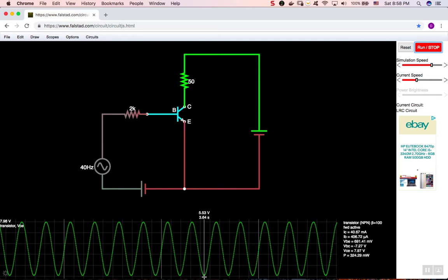So the voltage that appears across VCE is the same shape as the voltage across the small AC voltage source, but here the voltage only goes from half to minus half. So the range is 1, whereas here the voltage goes from 5.5 to 8. So the range is 2.5. So you can say that it amplified it 2.5 times. Maybe the gain, I'm not sure if it's proper to use the term gain here, but if it is, then the gain is 2.5 times.